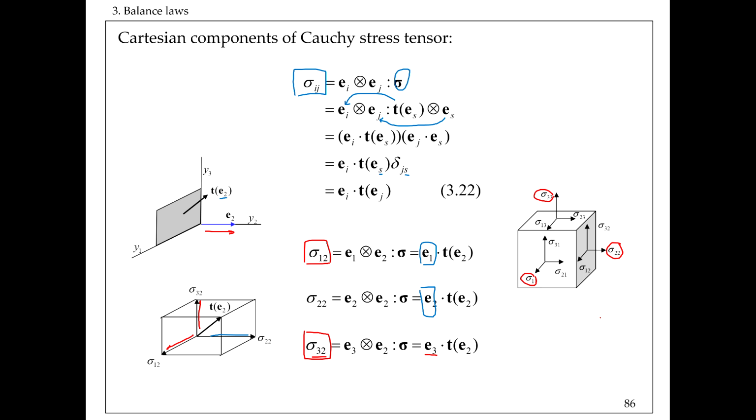It can be related to the calculation of traction on a surface, but then you really need to specify the surface by the normal, and you will see that the traction will depend not only on what this point feels, but also on the angle at which you come and cut this cross section.